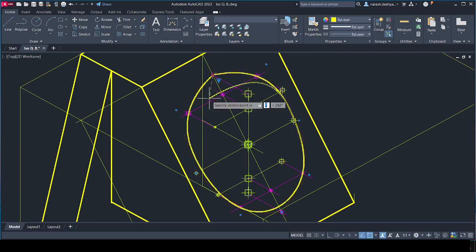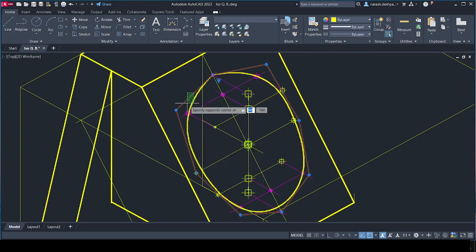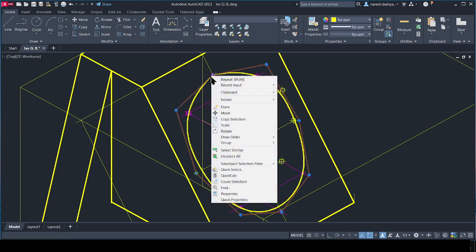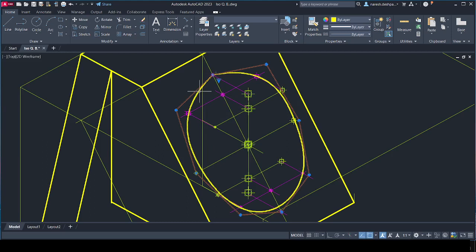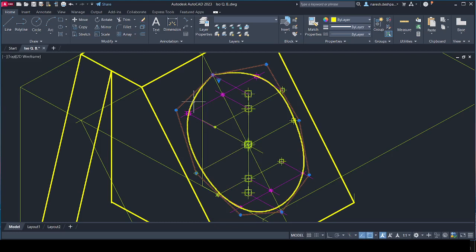You need to add one vertex there. Okay, we'll do that. We'll add one more vertex here. That is possible. So click on this, right click, add vertex. You should have the command to add the vertex there. Okay. So we're showing the properties only.